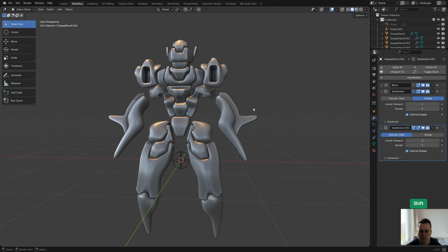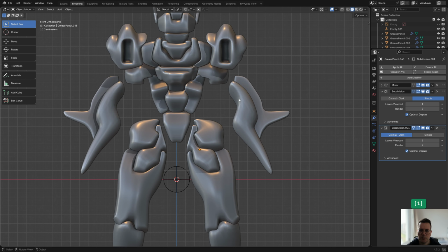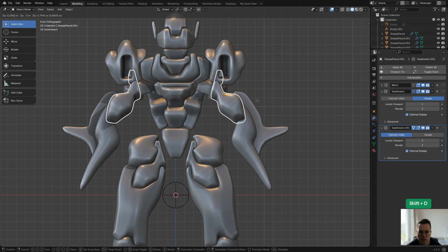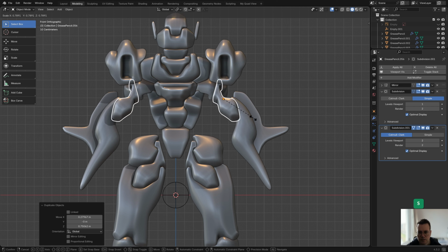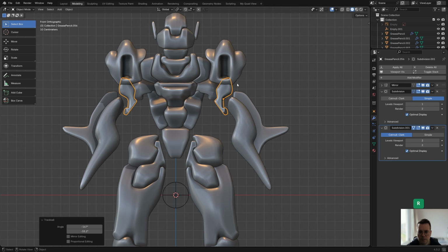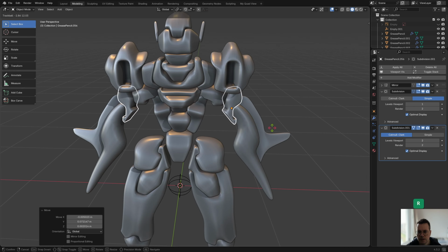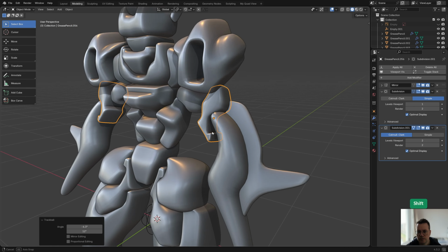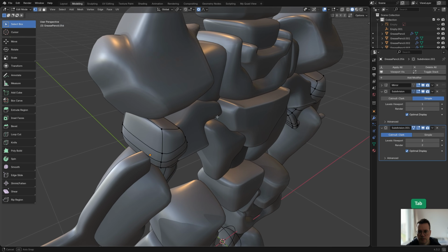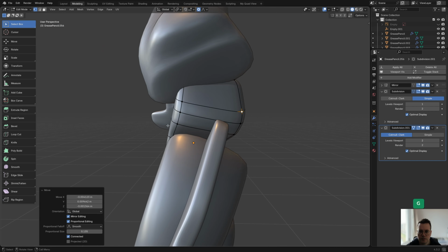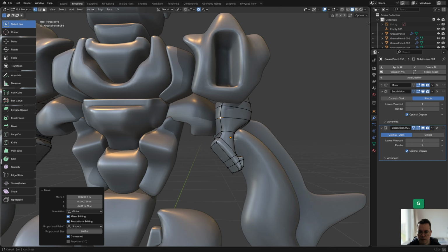And in some cases, like for example here, there's just a big gap between these arms. That's because I didn't draw anything in there in the design. One thing you can do to solve that real quick is select one of these objects and press Shift D to duplicate it. Then you can try to rearrange them, maybe make them fit like this, for example. And let's see from the side, and just press R twice if you want to have free rotation. Then of course we can still adjust this object. With proportional editing enabled, we can still fine tune the shape so we can make it fit better in this location.